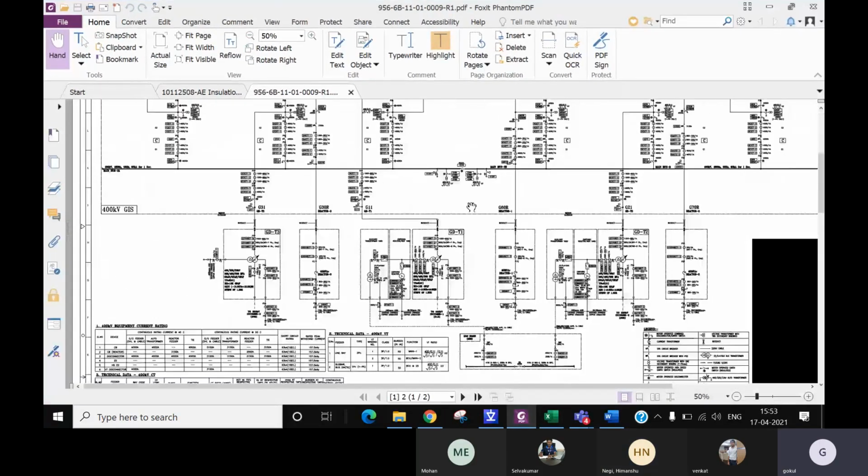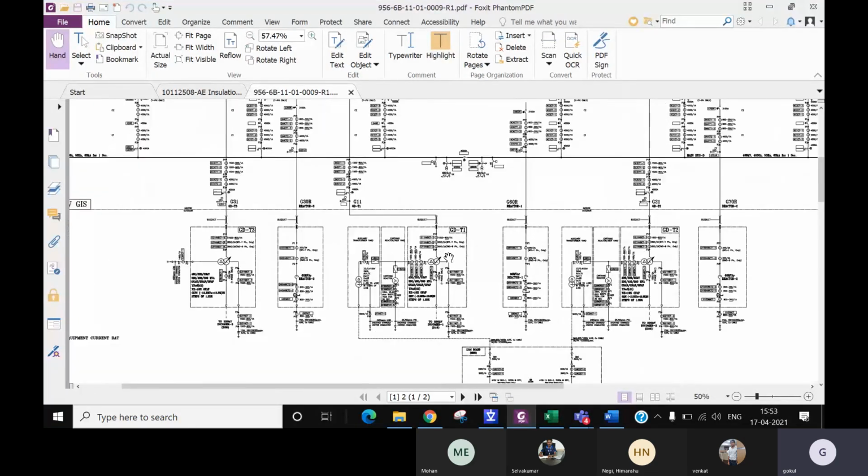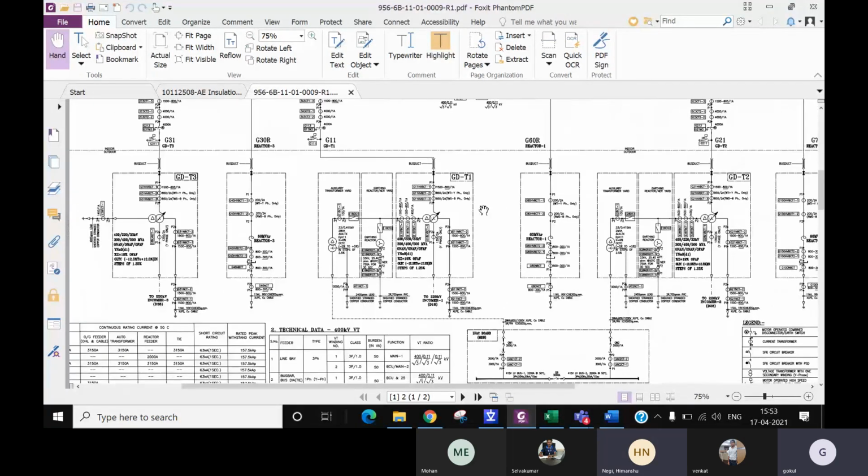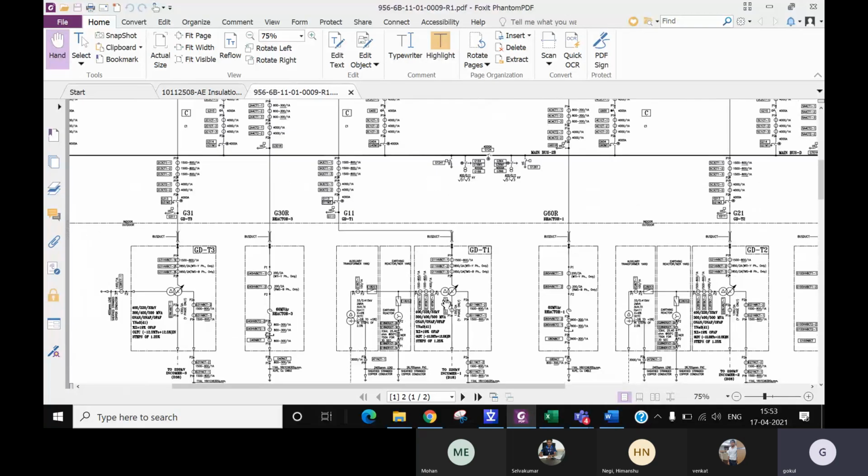So this is our SLD, right? We have shared this also. This is one of the transformers. And basically, what is ferroresonance? Ferroresonance involves a non-linear inductance. If your system has a non-linear inductance, the interaction between that non-linear inductance and your system parameters is basically ferroresonance, and that causes some oscillations, and that may give some overvoltage. That is the basic thing about ferroresonance.